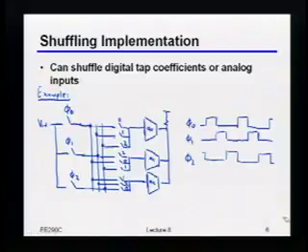Does that make sense? Or, by the way, there are actually some pretty clever things you may have to do to get the link to talk to its own transmitter, because if you think about these big, complicated backplanes, the transmitter associated with your receiver may not necessarily be talking to the receiver associated with your transmitter.